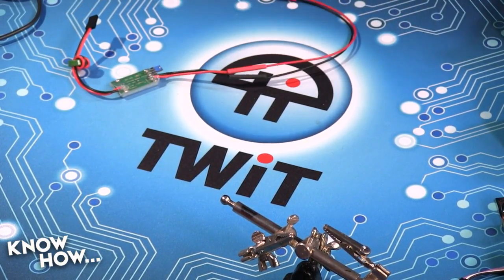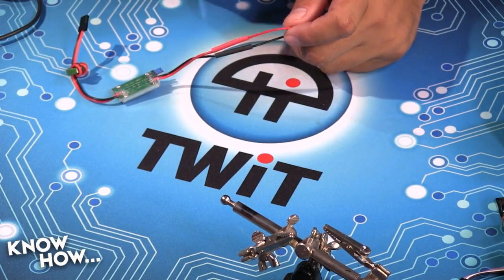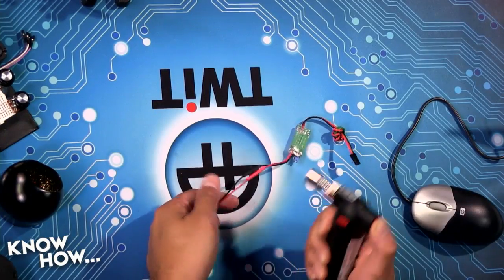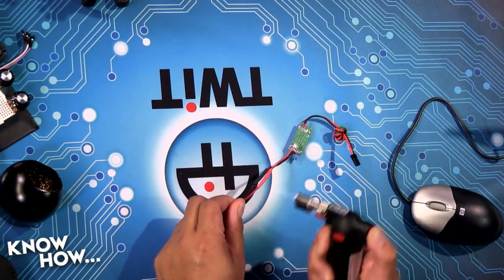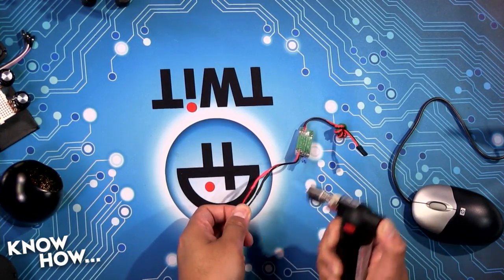And then again, you really should have a heat gun for this and not do it this way, but we're bad people here on Know How. If you are going to use a torch, move it quickly. You don't want to burn the tubing. You just want to heat it to the point where it shrinks.